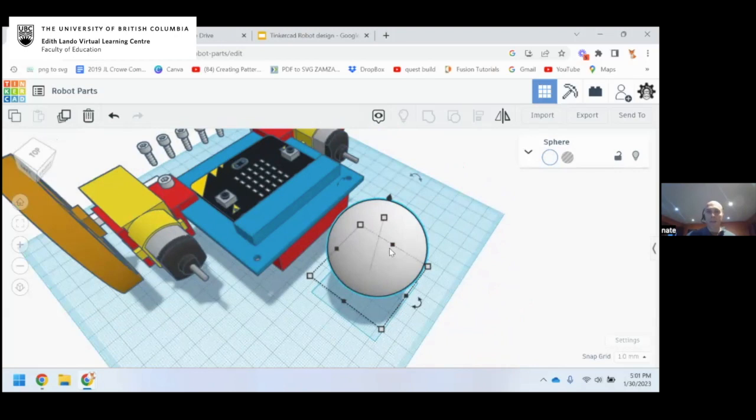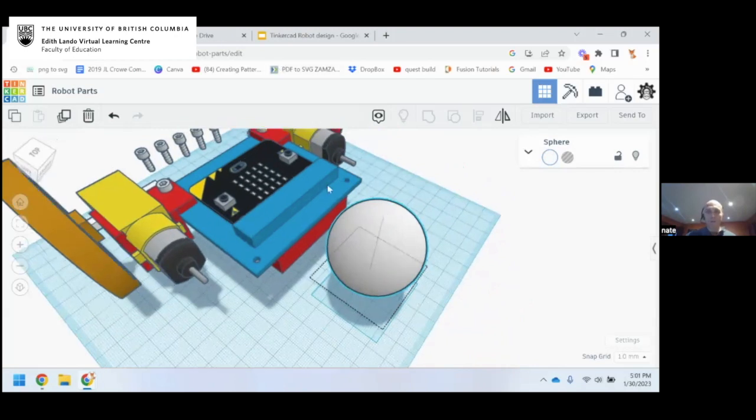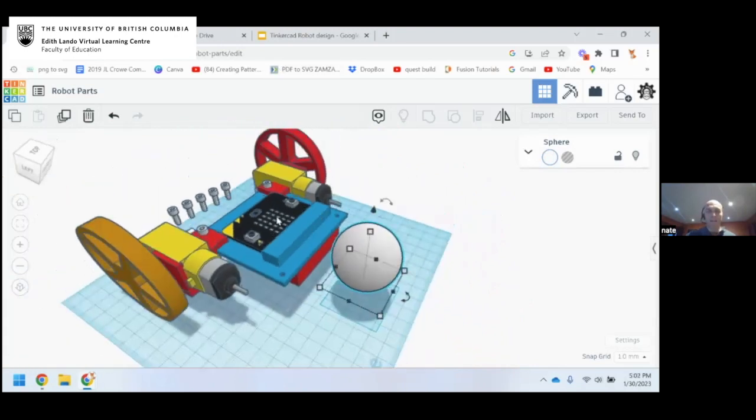A really handy tool, if you get into designing things in 3D printing or anything like that, is a digital caliper. They are a necessity for measuring small measurements and getting precise measurements. So we have digital calipers through all of our schools in different classes as a set that the students can use to open and close and measure out things precisely and then bring it into Tinkercad.